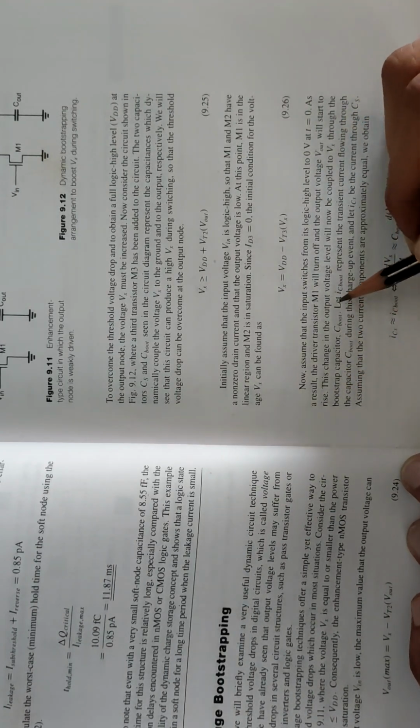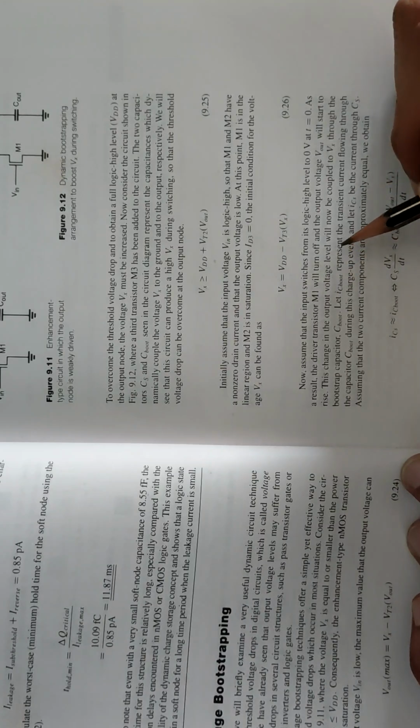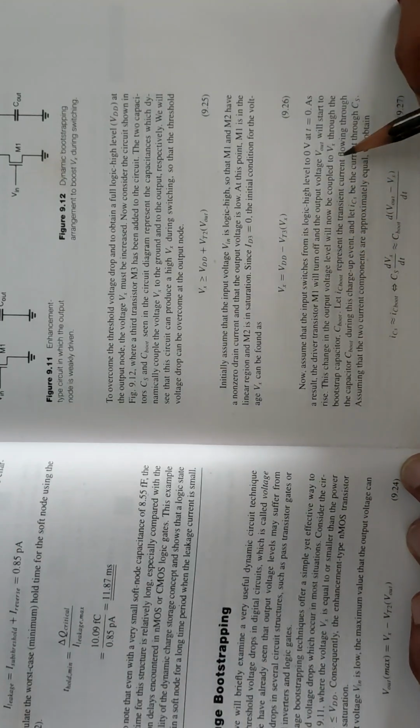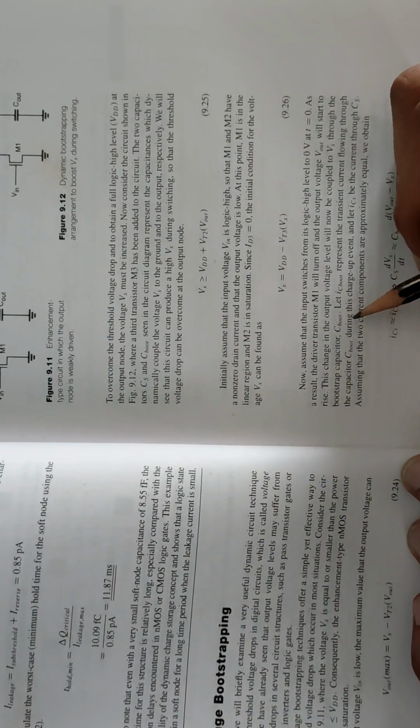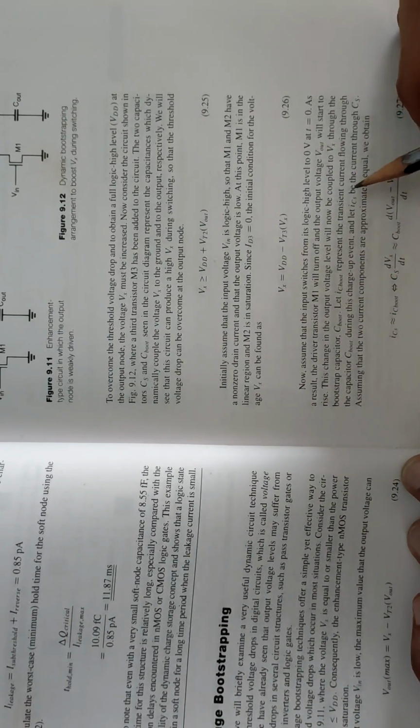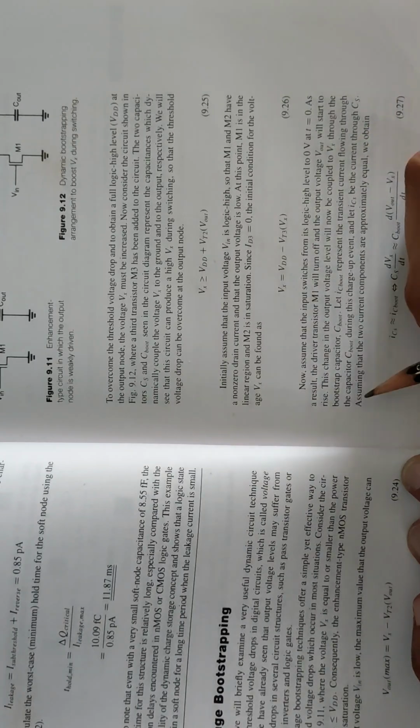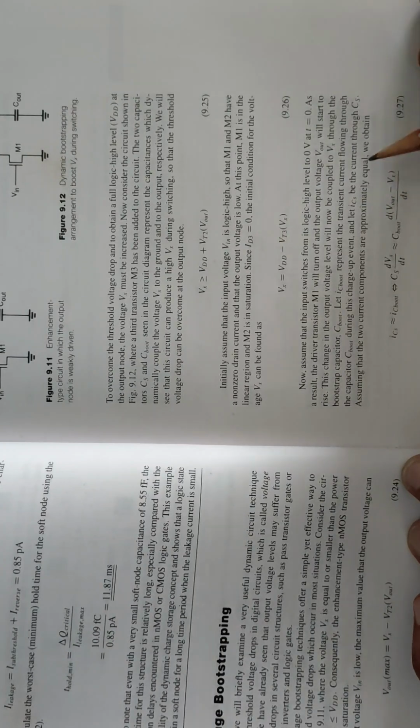This change in the output voltage level will now be coupled to Vx through the bootstrap capacitor Cboot. Let ICboot represent the transistor current flowing through the capacitor Cboot during the charge up event. Let ICS be the current through CS,